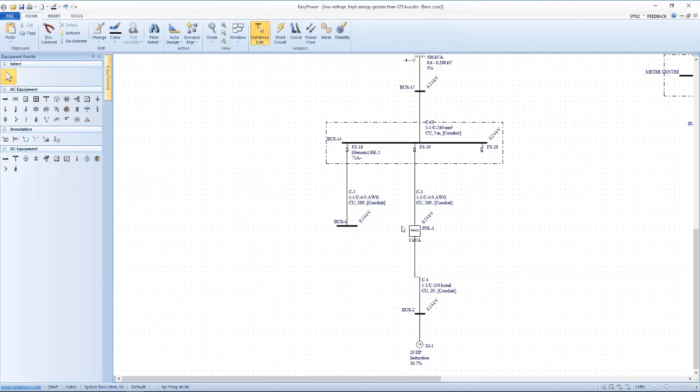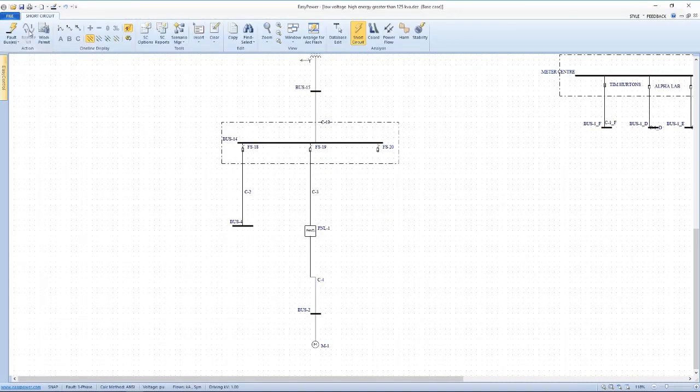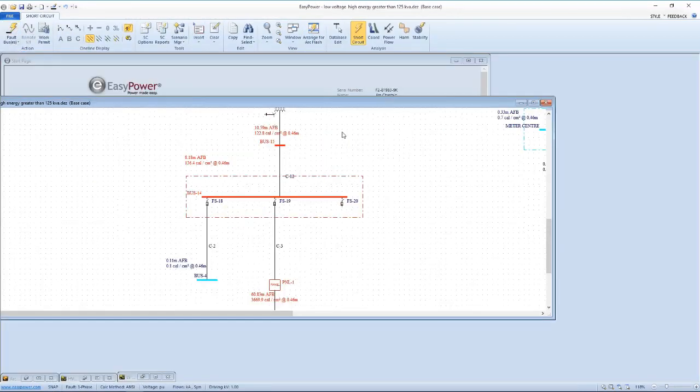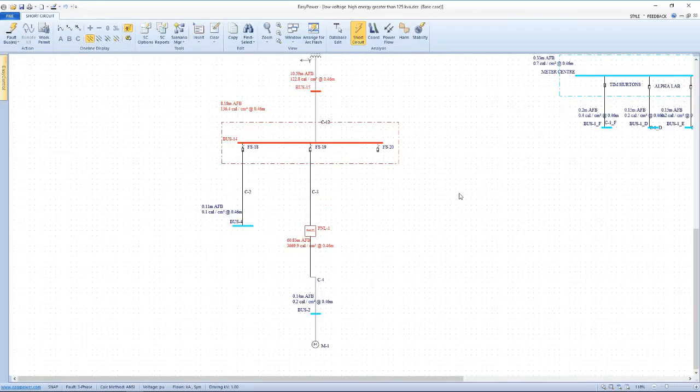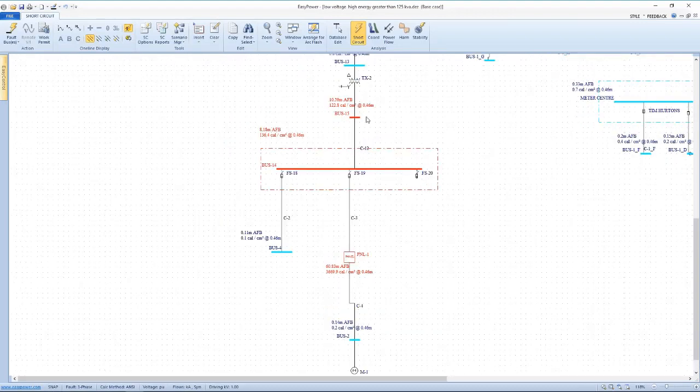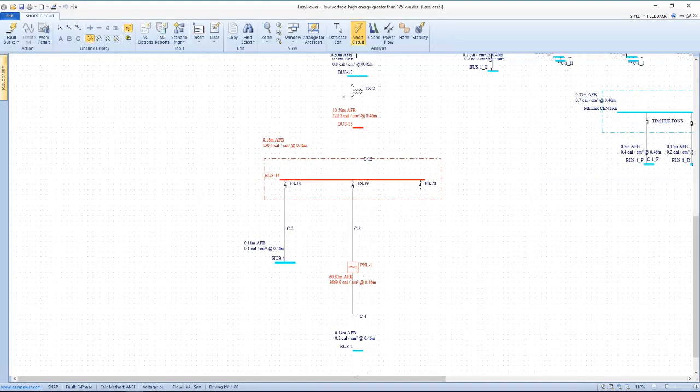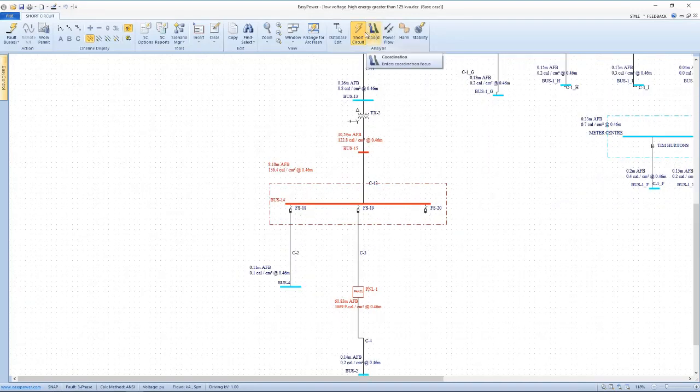All right, so the trade-offs are, when I use a panel schedule, I don't get labels for each load, and the upside is I reduce the number of buses in my total bus count by using a panel schedule or an MCC for that matter, which could be 20 or 30 loads, and remove that many buses from my total count. Okay, I probably beat that one into the ground. The answer that you were looking for, Brian, I think was yes. So it works either way.